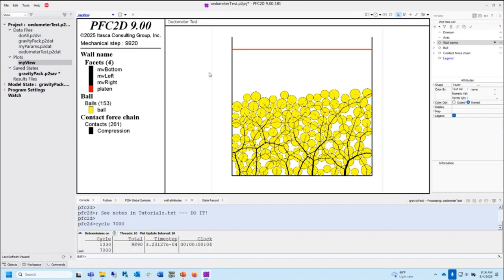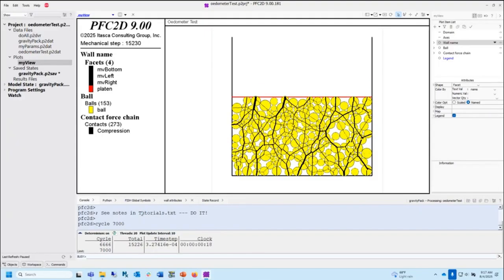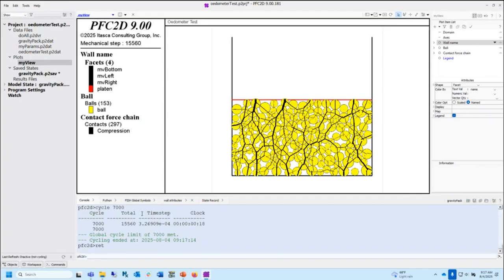And we haven't talked about anything about velocity or anything. I just screwed around and gave it the number that I did. And remember, PFC is computing a time step. You can't change that because that has to be done in order to properly integrate F equals ma. We know F equals ma, so we have to figure out what the velocity is, so we have to integrate it.